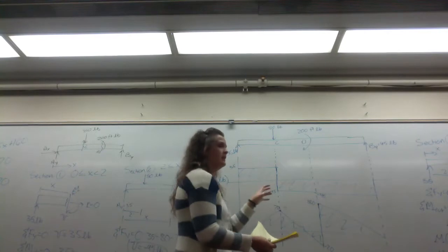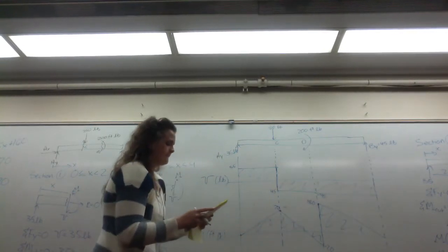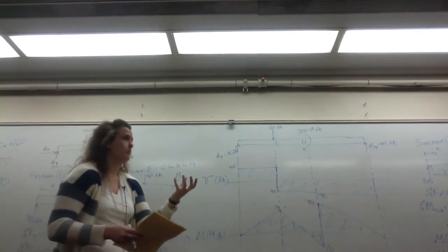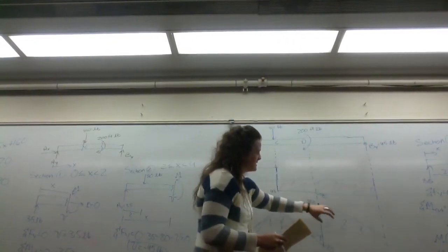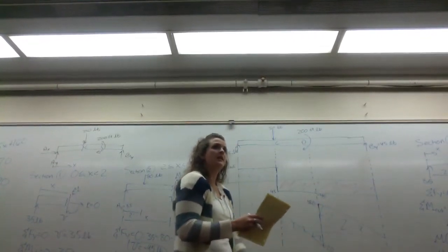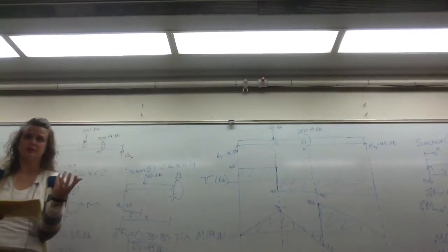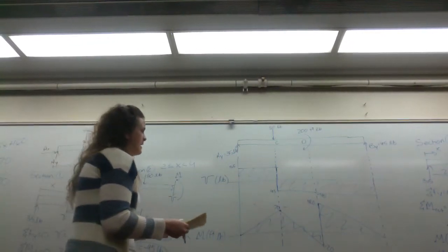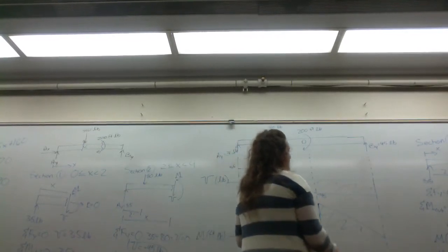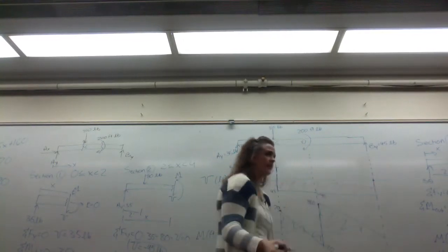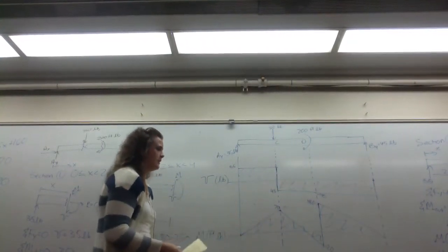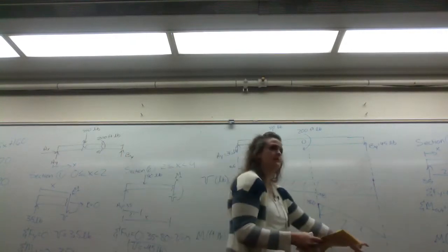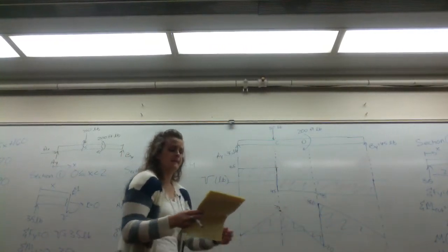Similarly for your moment, an applied moment causes an instantaneous change in your internal bending moment. All right. And also check that at connections, at fixed or pin connections, your moment is 0.